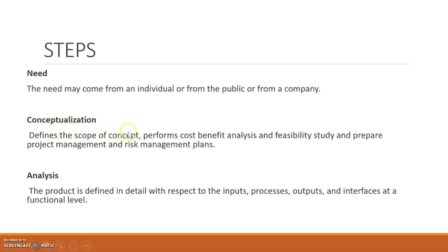Next is conceptualization. Conceptualization means we are going to make a concept, that is, we are going to conceptualize these things. That is what is the requirement, what all things need to be done to make the product work in such and such manner. And also we'll be analyzing the performance, cost, everything. And the feasibility study means, if you are going for this kind of a machine or a device, then what is the feasibility of the device to work in a proper way. Then risk management, project management, everything we are going to do in this conceptualization. And we'll be making a document out of it in most cases. And that is called the embedded systems concept document.